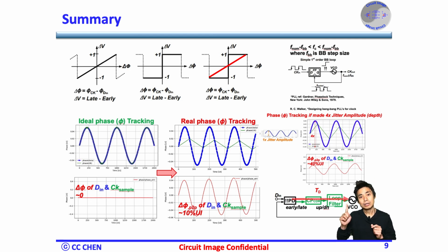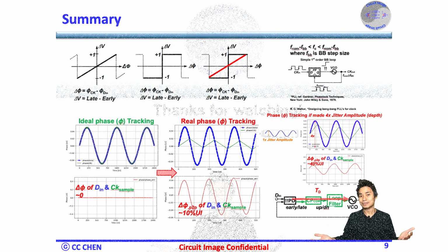and big jitter. So we should show the loop latency impact on the limit cycle and phase error from our modeling. Again, we will provide more latency impacts in another video in depth with a more refined model close to the real circuit. Then we plan to include the circuit noise in the modeling to complete a more precise system link budget in another video.